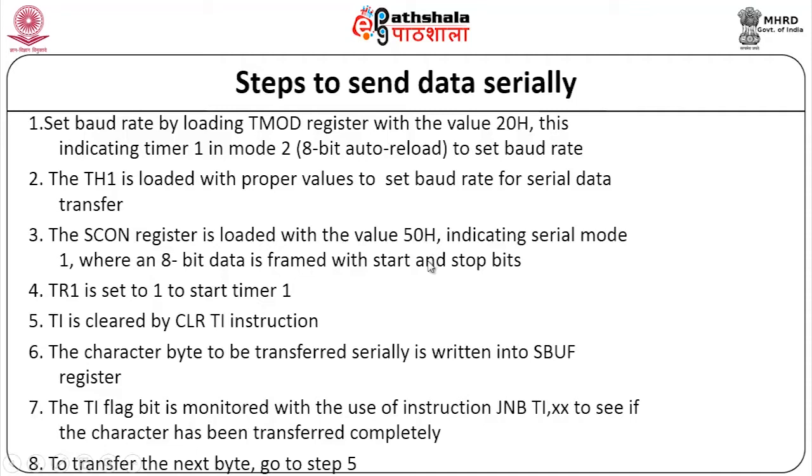So 50H is moved to SCON to ensure that serial communication can be invoked, and TR1 is set to 1 to start the timer, which maintains the baud rate properly. While you want to transmit or receive, by then we have to start this timer.